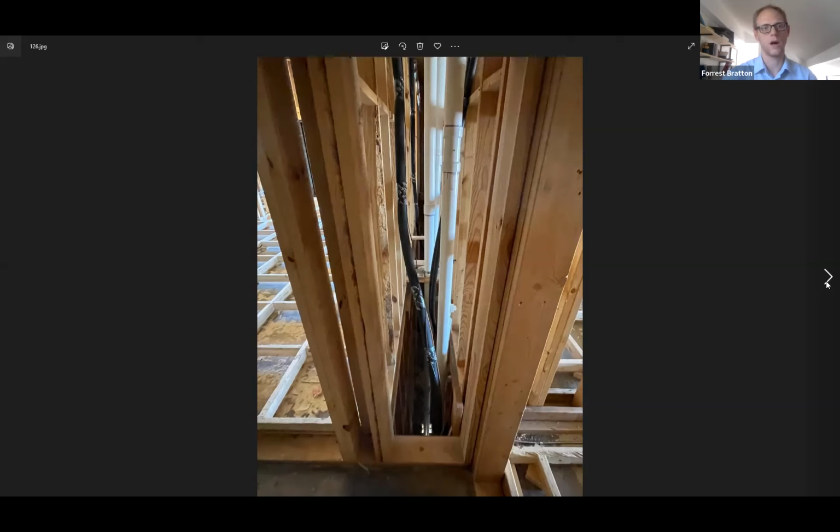In our case, at the upper floors, the chases were helpful. We could have bearing walls around them, so it wasn't too much of a challenge to support the panels around those chases. We weren't trying to make the panels do all the work to span around it. Generally speaking, I think our MEP engineer friends would agree that planning for a little bit of extra chase space always makes your life easier in the field.